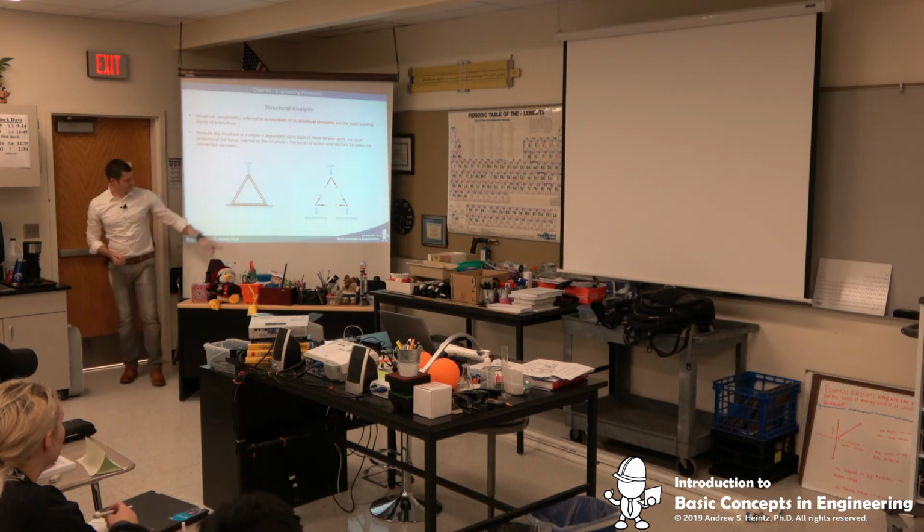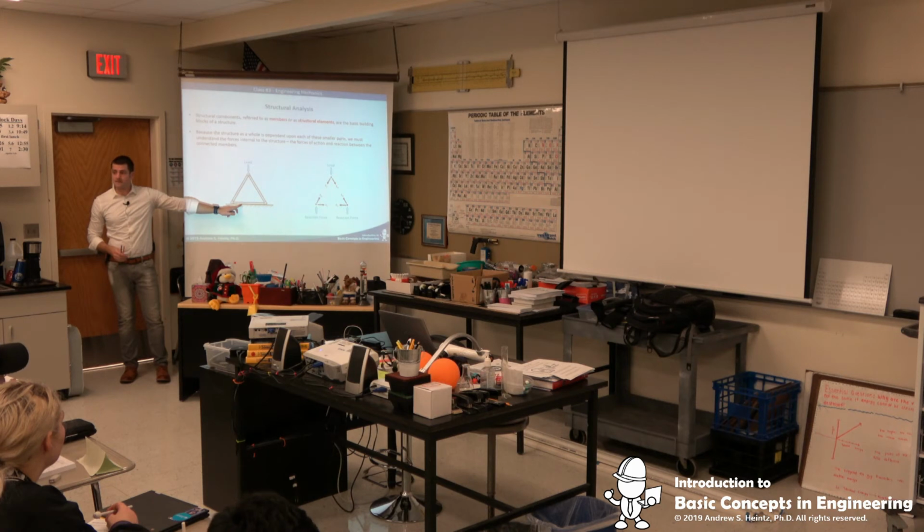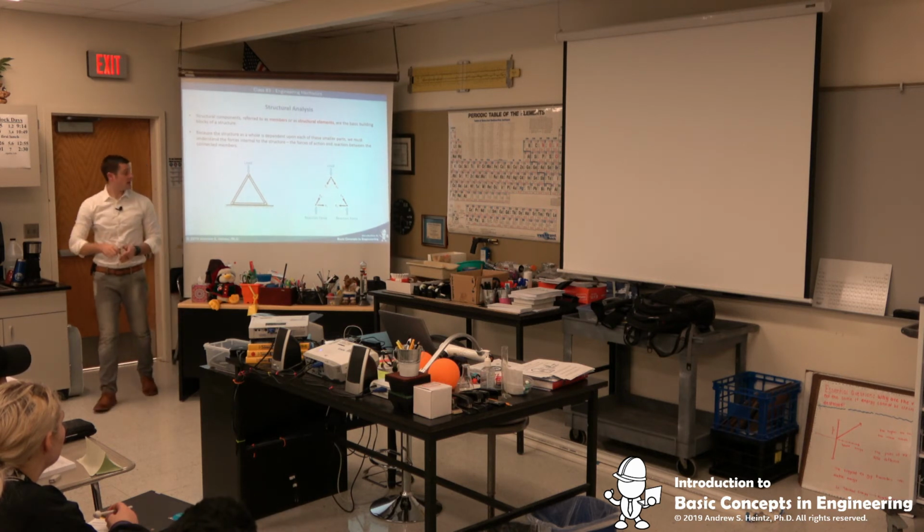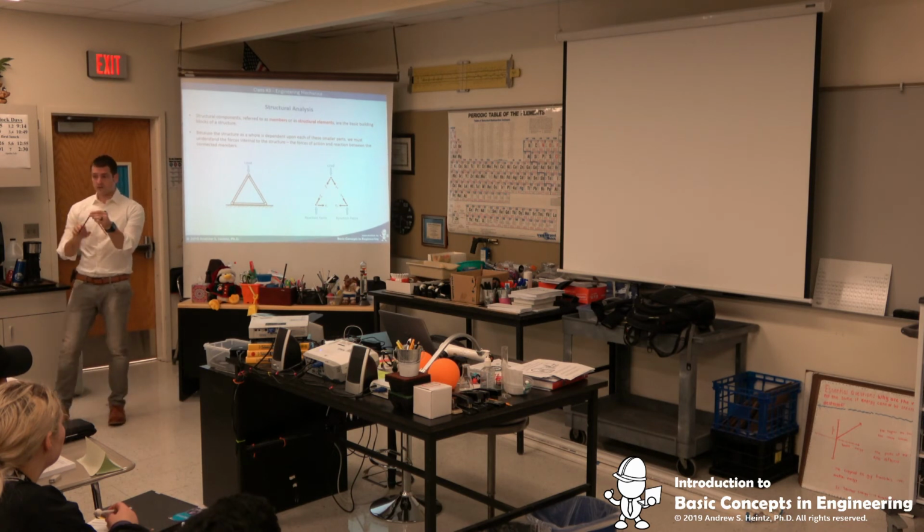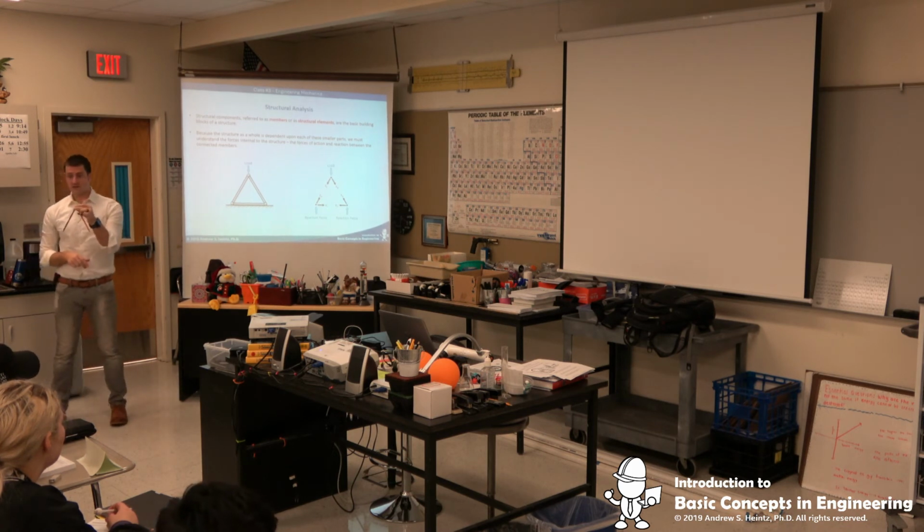And that's why we have this third member here at the bottom. What is this guy doing? He's holding them together, right? So you just nailed it. You said tension, okay? So we all agree that the structure as a whole is under compression, right? We all agree that we're being squished. So the structure as a whole is being squished, but is each member being squished? The answer is no, because of what you just said, sir.